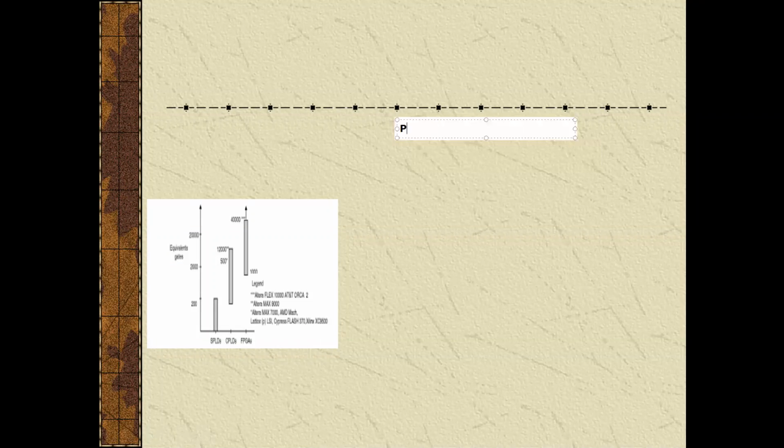So let's see the PROM. PROM is nothing but programmable read-only memory, which is a device that includes both an AND plane and an OR plane within a single IC package. Of these two arrays, the AND plane is fixed and the OR plane is programmable. I will show it in a figure.